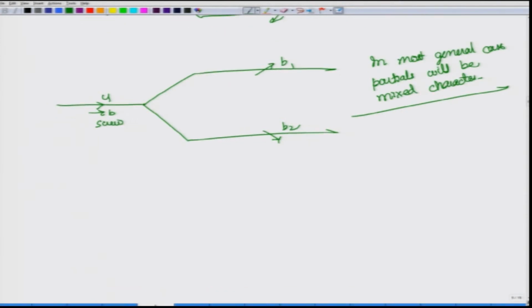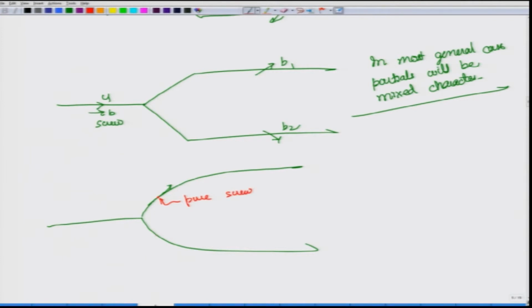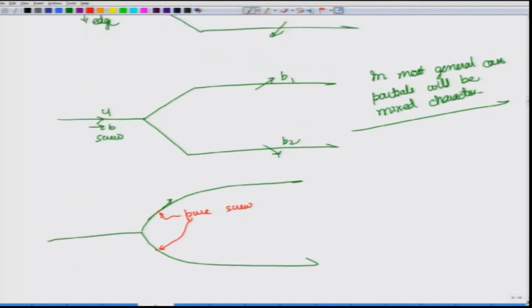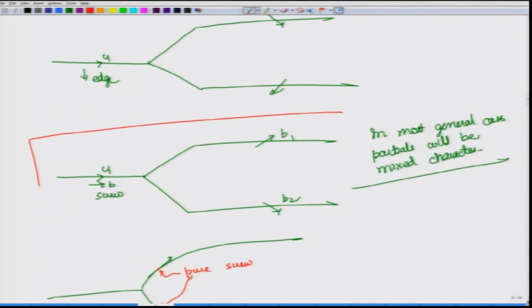Okay. Now, what I mean is that you can also have a line going like this, and since the Burgers vector is like this, somewhere over here it may still be parallel, somewhere it may still be perpendicular. So, just like in our regular dislocation, there may be certain points which are pure edge and pure screw. So, here it is pure screw and so on. So, here also this will be pure screw, but in general it will have a mixed character. However, what you have to go back and look at is whether the net force comes out repulsive or attractive.